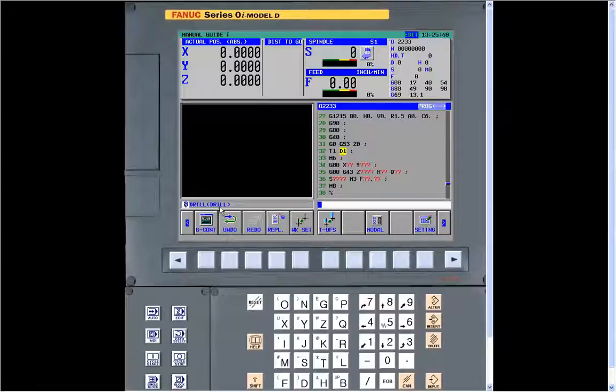See, as soon as we do that, it comes up, okay, it's a drill. That's what we want. Our position move is 0, and halter in X and Y. Our positioning move in Z is 1 inch. And then it's H1 is our tool length, and Z1. Now this tool, again, we're going to run this at 3,500. We got a good solid carbide drill. And our feed rate is 10. Again, this is just making it active. Again, M8 is turning on coolant.